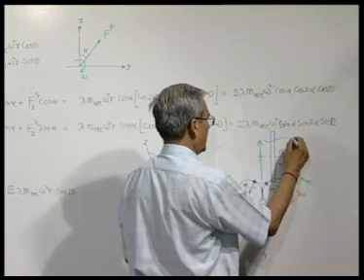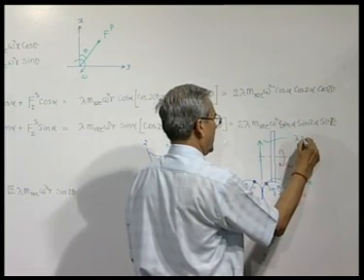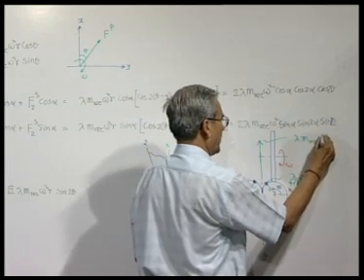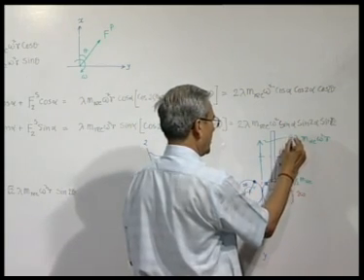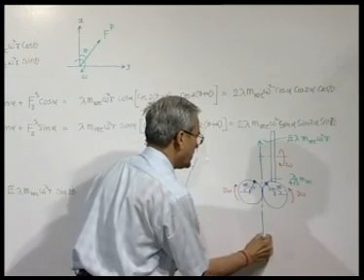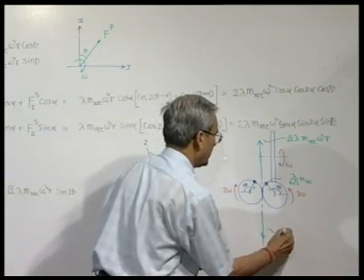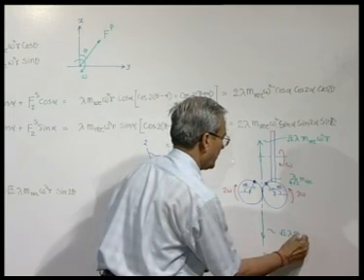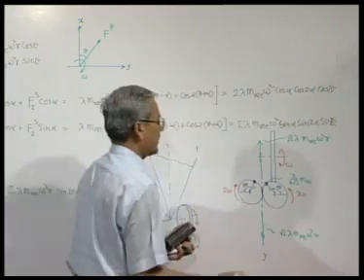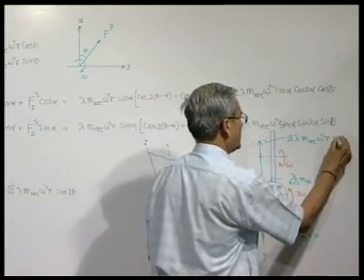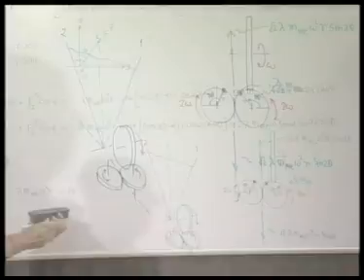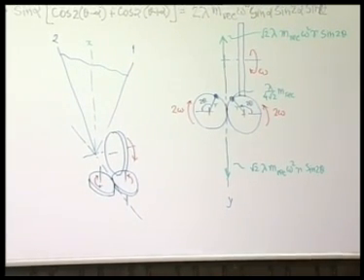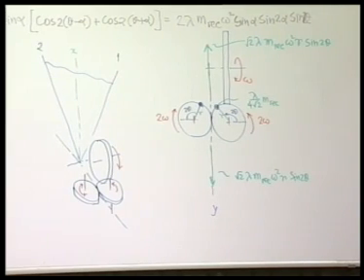So, it will be lambda m reciprocating omega square r, this 4 cancels because this is 4 omega square, and multiply by 2. So, here will be 1 2, and the original unbalance produced by the two engines is the same again. And here of course, this component will be sin 2 theta, and we already know sin 2 theta. So, thus at every instant the force developed in the engine can be balanced by the two centrifugal forces rotating in the opposite direction at every instant.